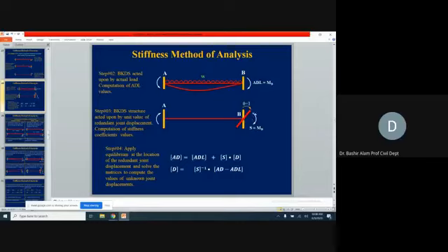How much rotation should we have here so that we generate an action, which is a moment in this case, equivalent and opposite in nature to this M moment, so that when we add up this moment generated and this moment generated, we get the final moment, which is 0 in this specific case. This way we can put this joint in equilibrium.